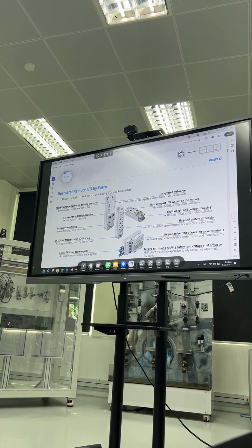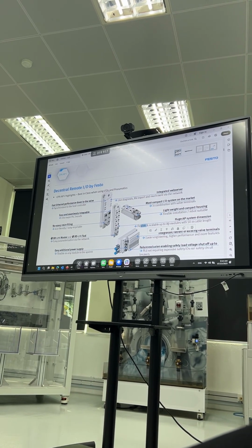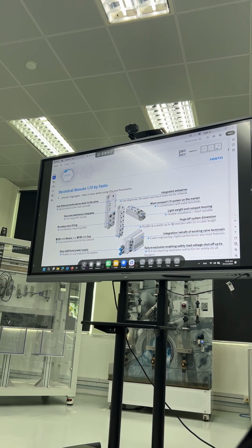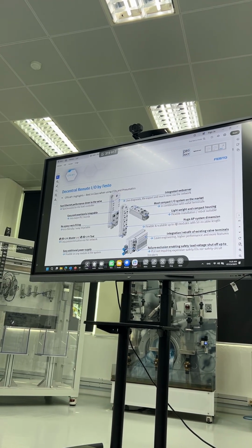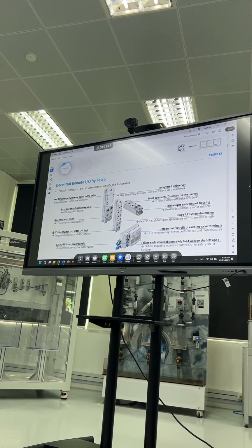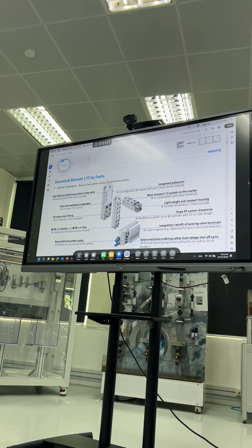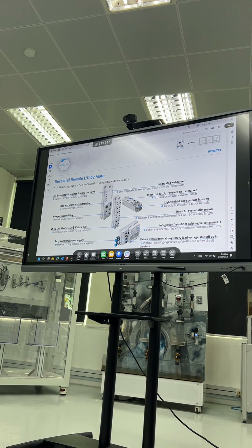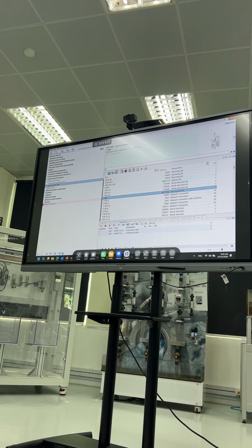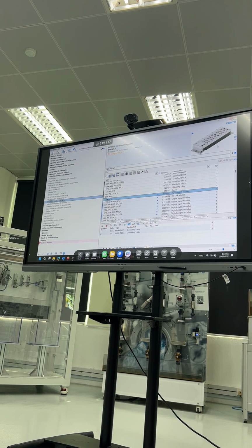Then for the CPX AP device, you can connect up to 80 modules. Okay, so that means the interface is counted as one module, and then you can have additional up to 79 I/O modules. Okay, but of course this is provided that for each field bus, right, there is a limitation of how many bytes they can communicate. So let's, for example, we see here.